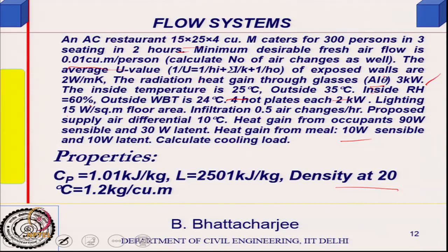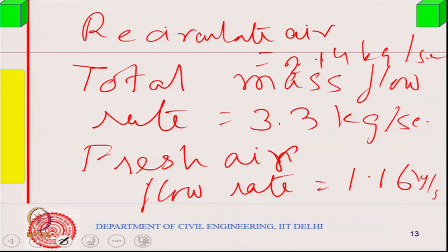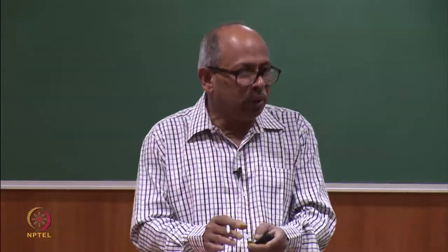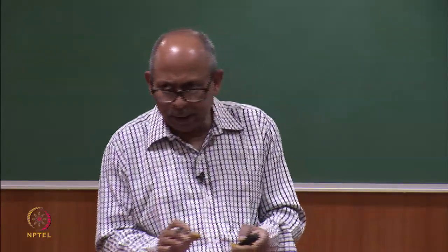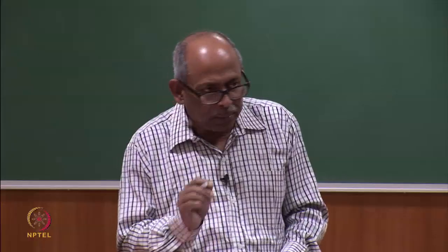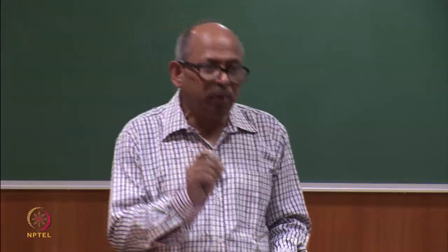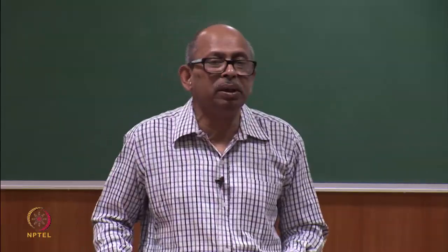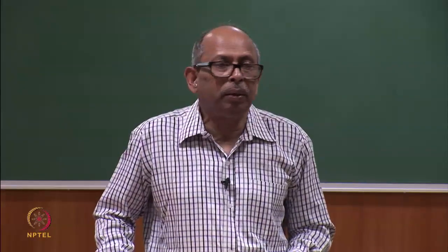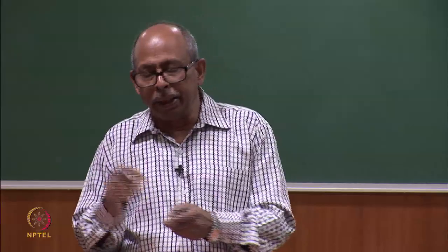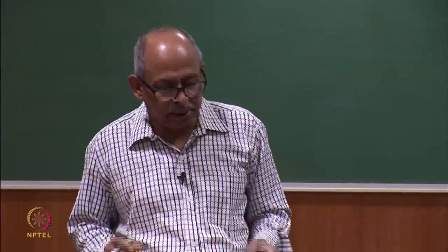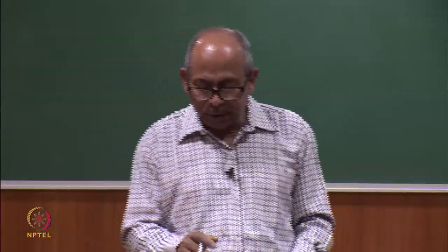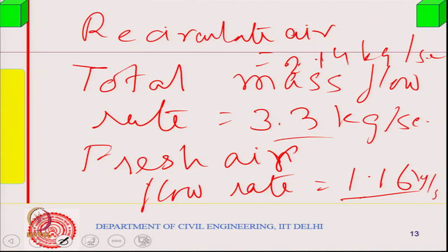So, calculation wise I think there was no problem, because 35 degrees is the outside temperature we have calculated based on this. I think we did not make any mistake so far, but supply air temperature would be 15 degrees, and corresponding moisture content we would like to find out, and how much cooling is required, actual cooling. Maybe the energy required would be somewhat different, because the efficiency etc. will come in. So, the first two steps we have done.